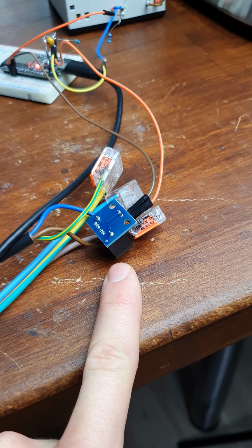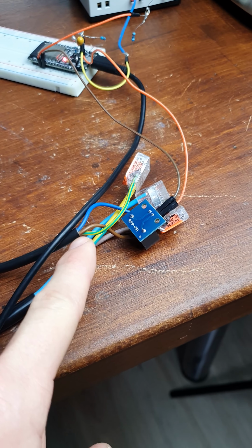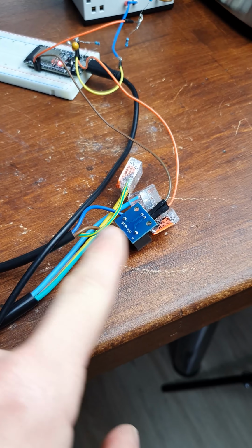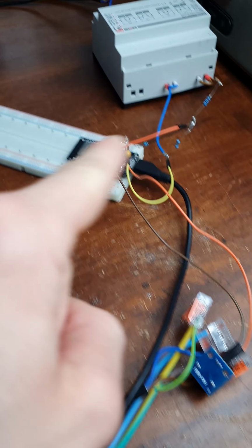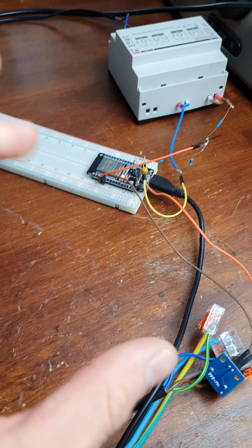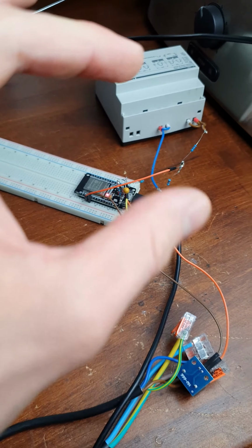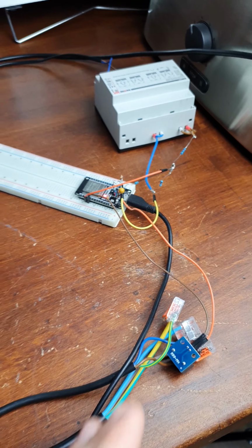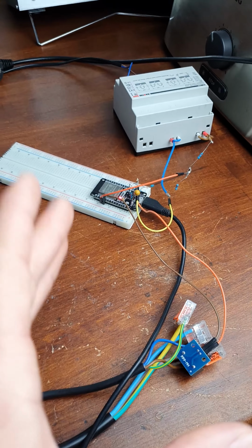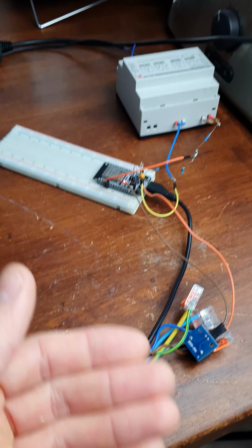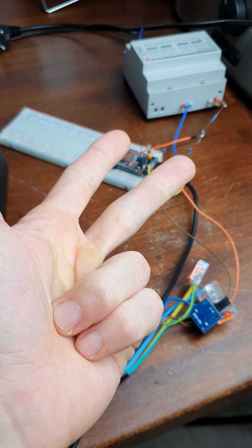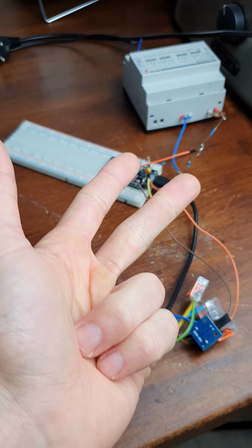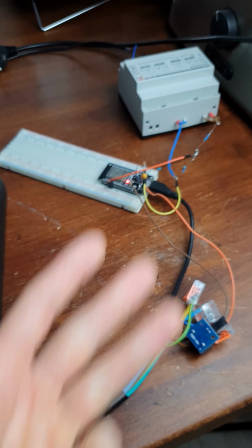It is a current transformer, which basically reduces the current flow, also creates this current waveform and then feeds it into the microcontroller. The microcontroller basically samples both waveforms at the same time. So it can calculate the real power, and then it also calculates the voltage RMS and the current RMS, and from that it can calculate the apparent power and then the power factor.